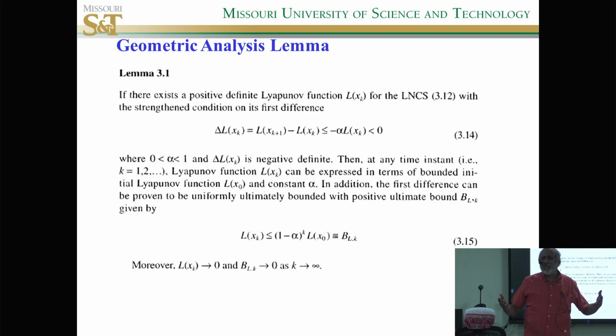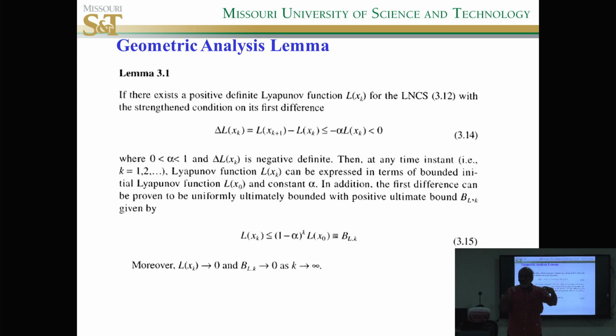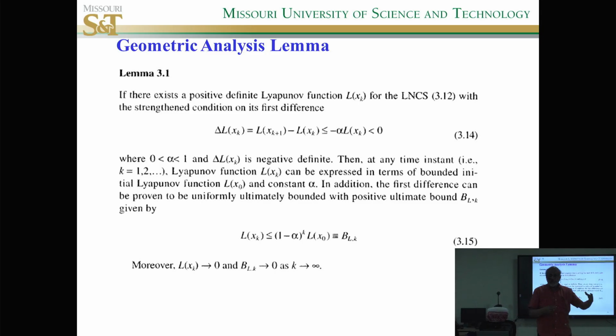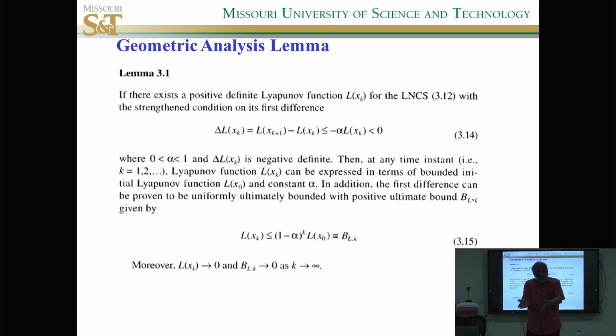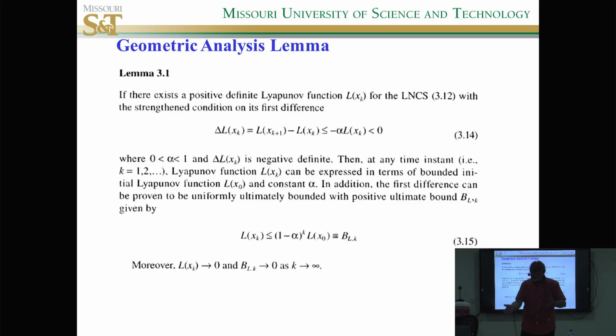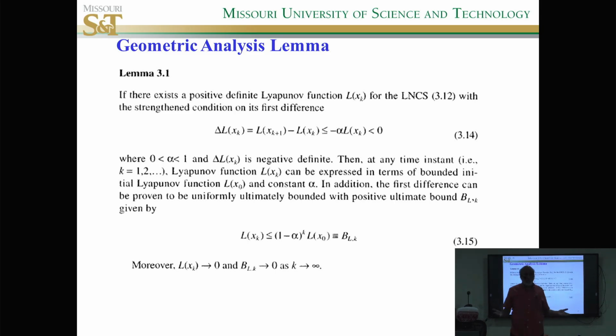Okay, and remember we did that in high school. Energy can neither be created nor destroyed. So it transforms from one energy to the other. The Lyapunov stability basically takes some kinetic energy and potential energy bundled together. That's your total energy. And you're looking at how the energy is being dissipated, right? And you know that when the energy becomes zero, just like a human, you basically become immobile, right? You just stop. So that's your equilibrium point. So that's what that is. So the minus sign basically shows it's decreasing, and ultimately it just stops at some place where the energy becomes zero. Okay? So in terms of Lyapunov, this guy is so powerful.